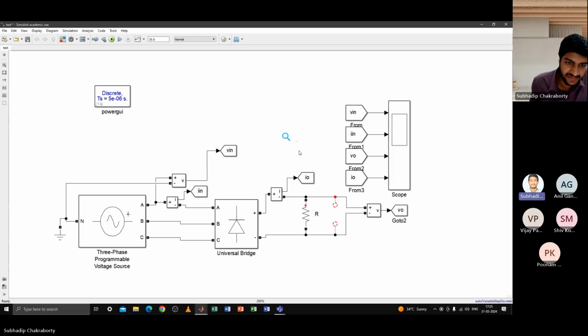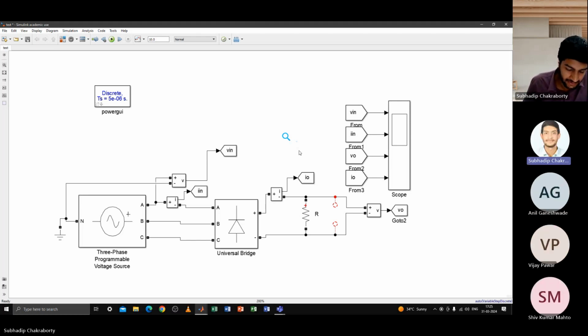Just remember one thing, that for shunt filter design, you just have to provide a low impedance path to the harmonics that you are designing that branch for, just as we discussed in the previous session, and ensure that the quality factor targets are also met. Accordingly, you will get the values of R, L, and C. Now check if they are providing reactive compensation, then your C value will be set, as you know how we set the C values for the 3 branches if it is a 3-phase 3-wire system or a single phase system. From the C value you calculate the L value, and after you get the L value, you calculate the value of R from the quality factor.